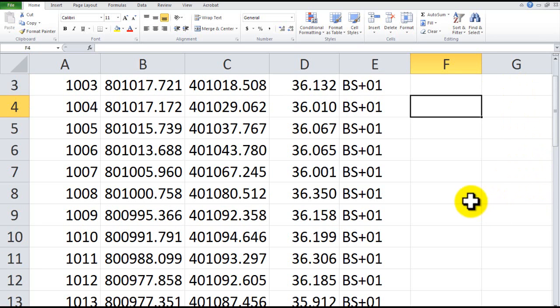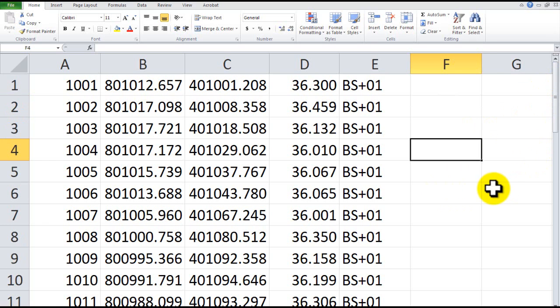So I'm going to load this data into our survey software, and it's related to a stockpile. I'm going to show you, one, how I go about loading the data in, and secondly how we might calculate the volumes. There's a couple of ways of calculating the volumes of the stockpile, but I'm just going to demonstrate that in some fairly standard survey software.